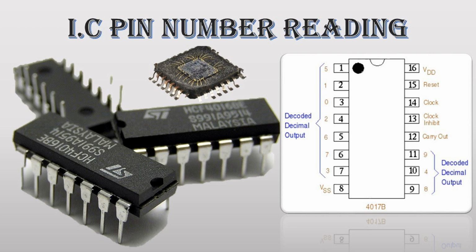Example, 1:4 DMUX. Input X. The input signal to be distributed. Select lines S0, S1: 2 select lines determine which output line receives the input signal. Outputs Y0, Y1, Y2, Y3. The input is routed to one of the 4 output lines based on the select lines. Multiplexers and demultiplexers are essential components in digital systems and data communication networks.